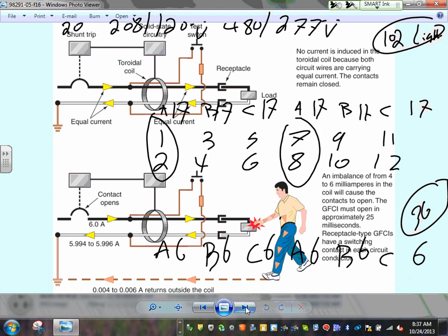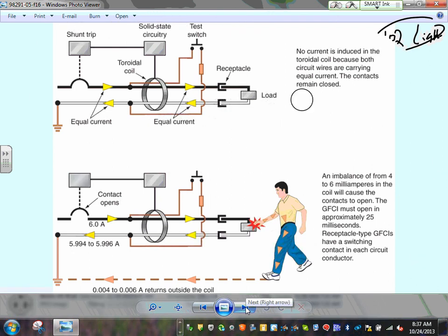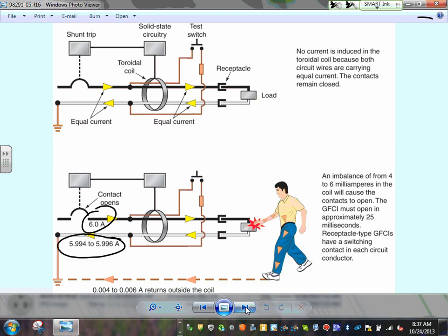The grounding, why do you use GFCI? You guys seen it on the residential project as well. They have an electronic circuit that senses what's going on. If the current is 6 amps going on here, there's a difference of 6 milliamps going back. That difference is going right to this gentleman's heart. The electronic device has a sensitivity to sense and measure and say, wow, there's 6 milliamps going through somebody's heart, and it trips fast enough, so this gentleman will go back to his family.